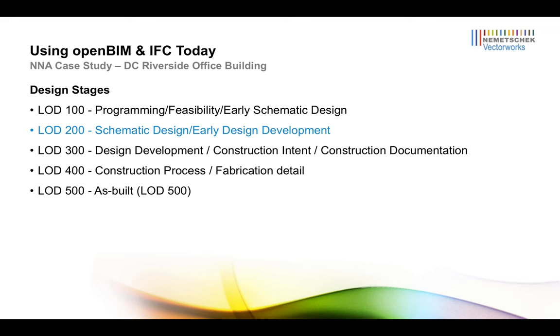Right, but I'm looking at it also on more of a micro level. Let's take a door, for instance. It's not just the model itself that is set at the LOD, but the components themselves. There's a certain amount of detail that's desired at different points in the project. At LOD 100, you don't really need to know anything other than a massing study.